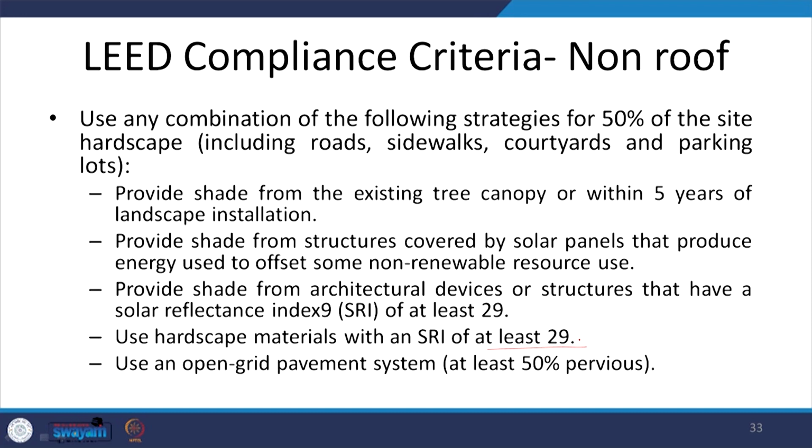Now, when we are talking about the non-roof areas in a site, we have to also see that the SRI does not go very high. Very high values of SRI imply very high reflectivity, and that can also be a cause of glare. So, the number has been limited to 29.